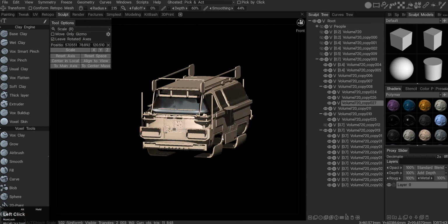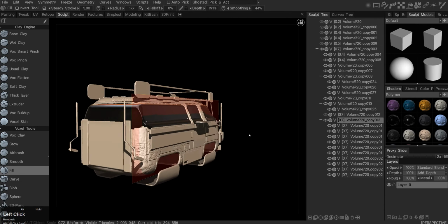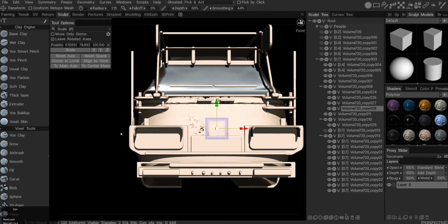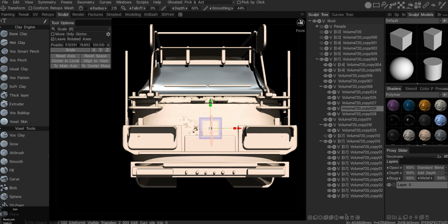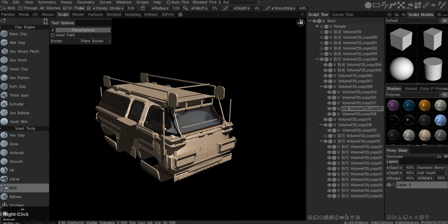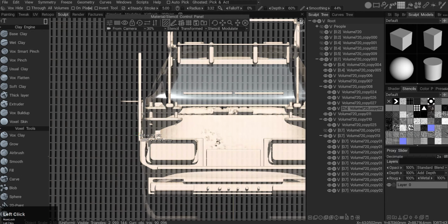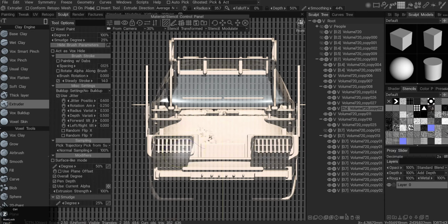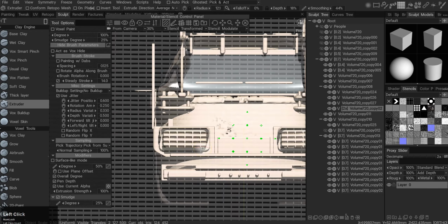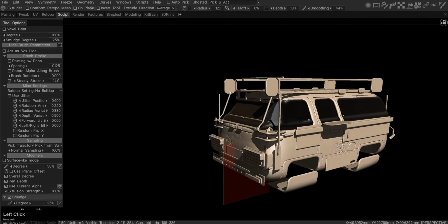So I was talking about the windshield having this really shiny glossy material. I didn't really paint the roughness into it. If I paint some dirty blurry windows, that would help to sell this being an old vehicle. And now I didn't have the headlamps, and I want to add some kind of pattern to that. So I'll go into stencil and start to play with those standard stencils. I'm using extrusion, and I'll set the depth a bit lower so it doesn't extrude through the whole thing. And I'm rotating the stencil so now we can have our pattern.